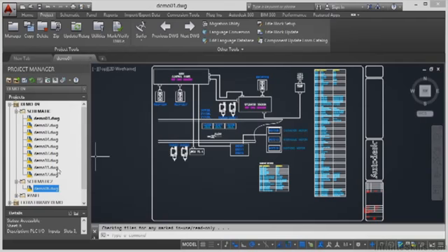So what we need to do there is we need to take some of these and put them into Schematic 2. So I'm just going to put a couple of drawings in there, like so. So Schematic 2 there. When it highlights, release, it puts that drawing in that folder. So when I minimize there, you can see that those drawings still show there, but Schematic 2 is now minimized. So that's how you group your drawings within your project in your project manager. Now that does not affect where they are located on your server, on your hard drive, on your portable hard drive or whatever. All you're doing is arranging them in the project manager in AutoCAD Electrical.